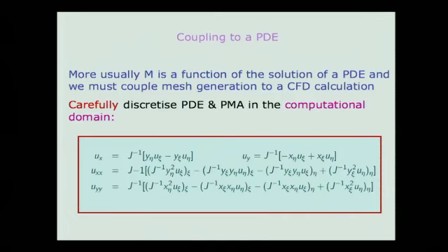When we want to discretize the equation, we have one great thing up our sleeve with this approach, in that we're going from a computational domain which has a beautifully regular uniform grid in it, mapping that into a physical domain. Where are we going to discretize? Well, best place to discretize is where everything is nice and uniform. So what we typically do when we do these things is we solve for the mesh, but always compute in the computational domain.